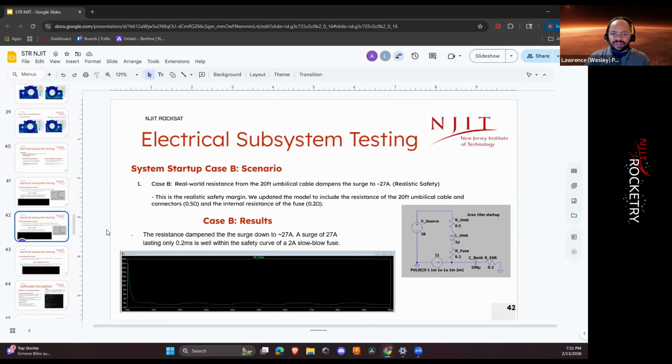If the umbilical that you're using to test is a little bit different than the harness that we're using, which it will be. But the one thing I wanted to mention, this is not a suggestion saying you have to, but one thing to consider that you may have already considered is just limiting it with an inrush current limiter, like an NTC thermistor or something. But again, it's so short. 200 microseconds, the only thing that'd catch that would be an E-fuse.